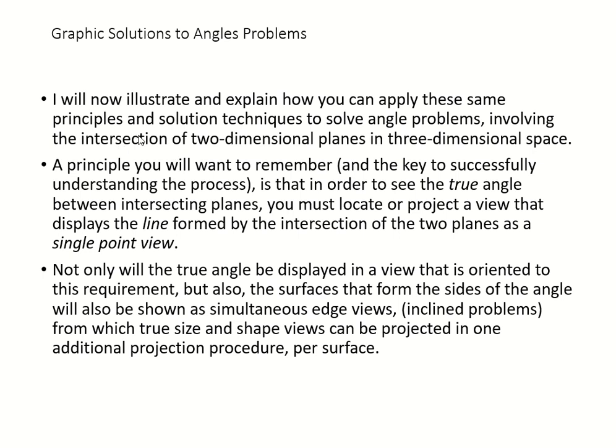True angle problems are again based on the intersection between two planes, two-dimensional planes, yeah? And again, our object is in three-dimensional space, while the views are 2D. So our method of solving this type of problem is to get the single point view of the line formed by the two planes that are making that intersection. Again, you can see it right now.